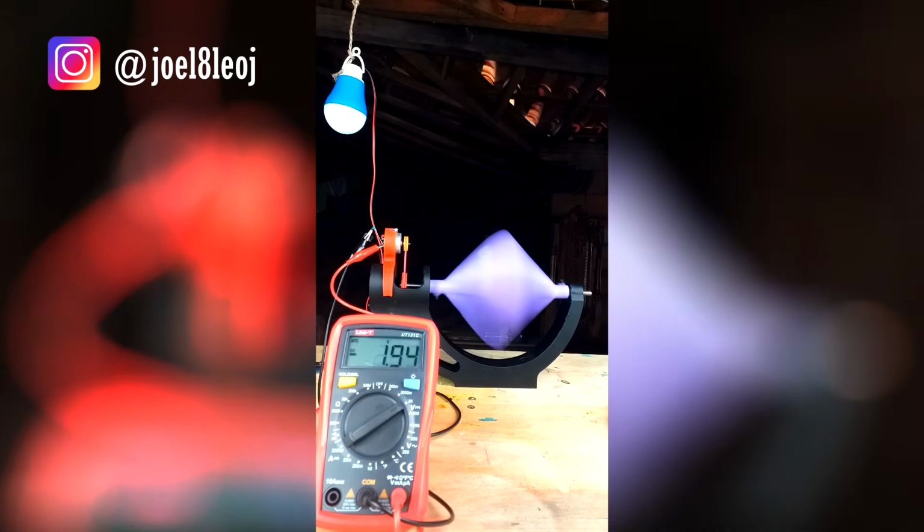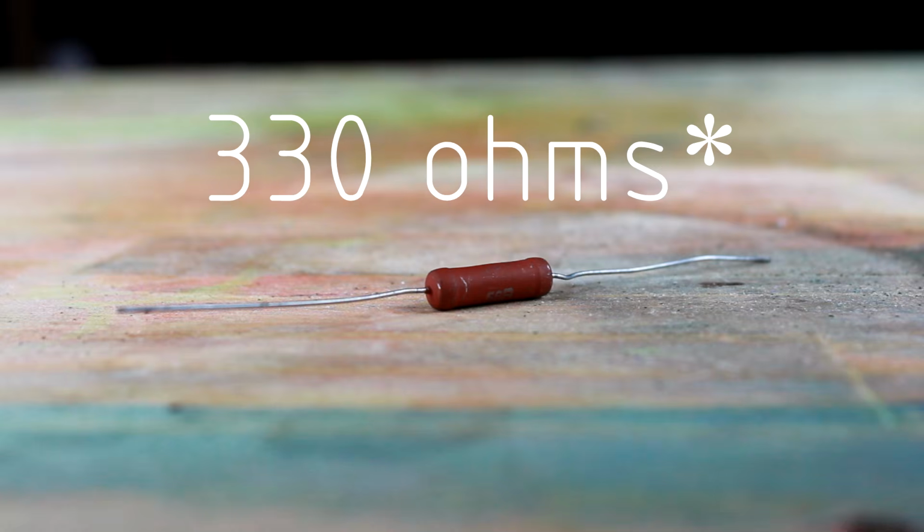Let's see. With a 330 ohms resistor and a voltage drop of about 9 volts, we get a flowing current of 30 milliamperes and an output power of 0.25 watts. A quarter of a watt? Are you kidding me? Enough of this.